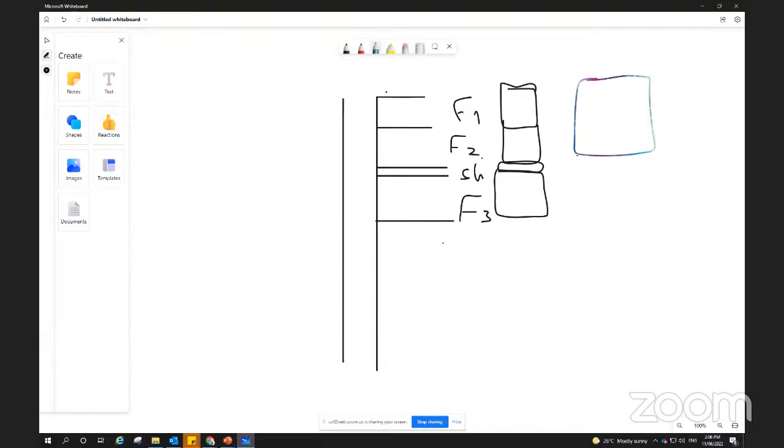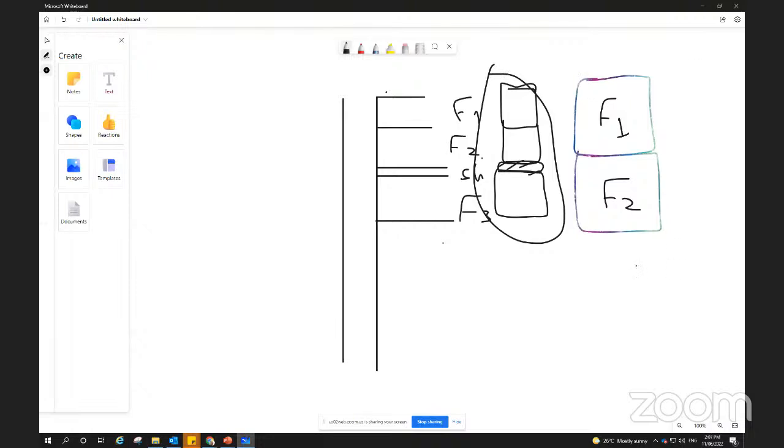The problem of the coarse grid with the geology is that sometimes it skips the fine intervals such as shale, because sometimes it cannot capture them. So we have a large cell for F1, large cell for F1, large cell for F2 or maybe F3, even if sometimes there is heterogeneity. The problem with the coarse grid is that it doesn't capture heterogeneity. With the fine grid that geologists built, it captures the heterogeneity, but the coarse grid, which is required for simulation, doesn't capture it.